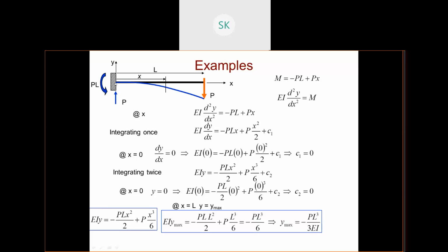Now there is no deflection. If you see the figure, there is no deflection at this point. Now you need to find the deflection at this point. This is the general equation. Suppose you have been asked to find the deflection at L by 2, that means at the midpoint. So replace this x by L by 2. This equation is giving y maximum, the maximum deflection.